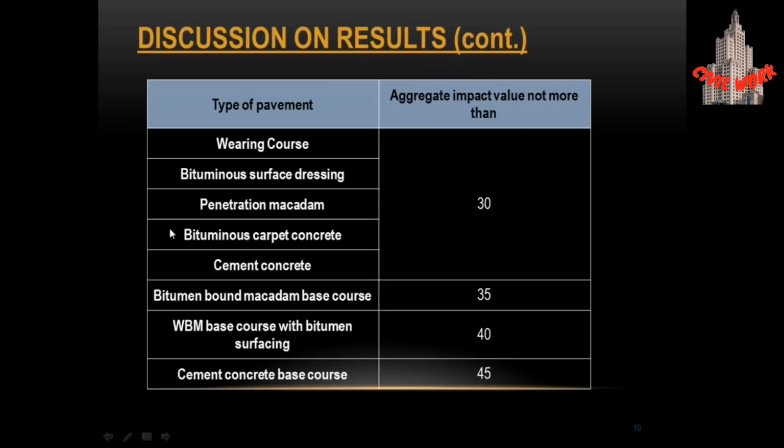Here we have a more explanatory discussion on results. When the aggregate impact value is not more than 30%, it can be used in the wearing course, bituminous surface dressing, penetration macadam, bituminous carpet concrete, cement concrete.